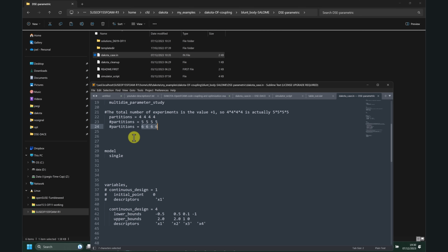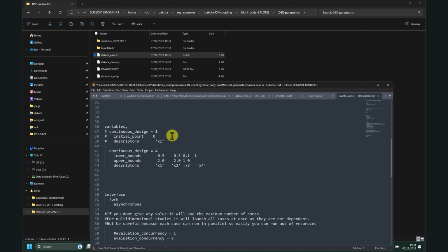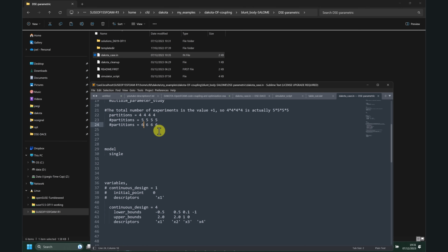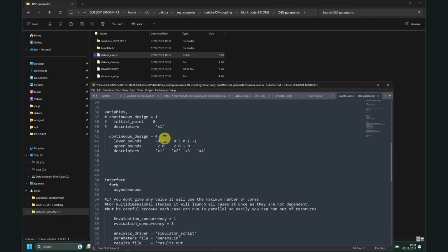But it is leaving a lot of holes, empty space in your domain space, so it's not very good. So to get something moderately accurate, you need to put something like 60, 60, 60, and well, you know that that's big. So we go into the order now, talking about turbulence like Kolmogorov scales, and to resolve those scales you need to be at the cube of the Reynolds number, stuff like that you will get here. So it's really prohibitive.